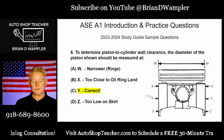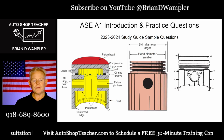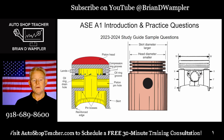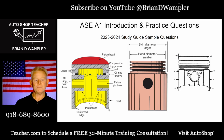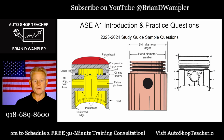And I know I kind of jumped to that quick. Let me back up here. Here on the skirt at the very end, the bottom, so I'm on the far left image. Hopefully you can see my little mouse pointer here. We wouldn't want that to be flared out, or as that piston's coming down through the cylinder, it could be scraping the cylinder wall. So it's typically going to be a little bit narrower.